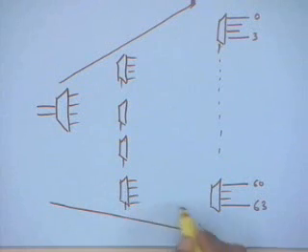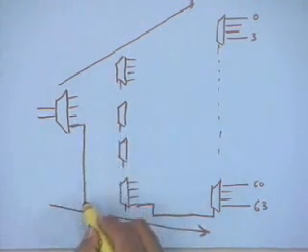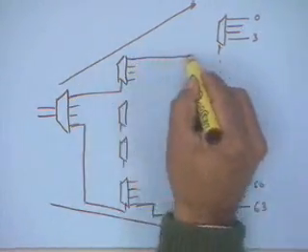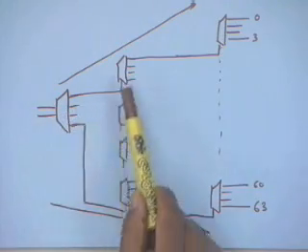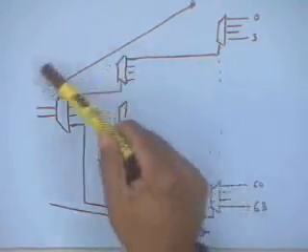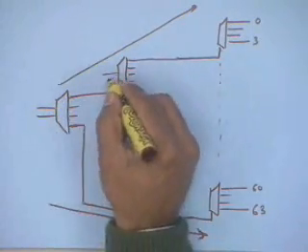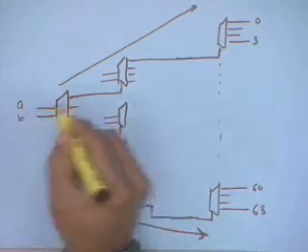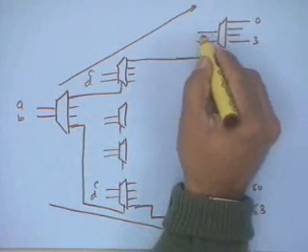And so because I am going to have 16 outputs, this is how it's going to look like. So I have 2 to 4 decoding, I have 4 to, actually if you consider this together, it's a 4 to 16 decoding, except that the variables I now choose, I have to choose appropriately. So this, let's say, corresponds to AB. So these are all CD, and these are all EF.